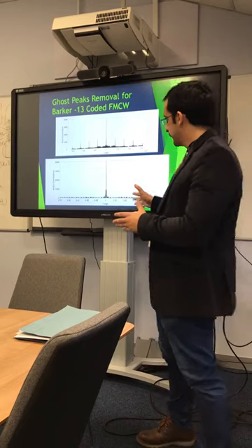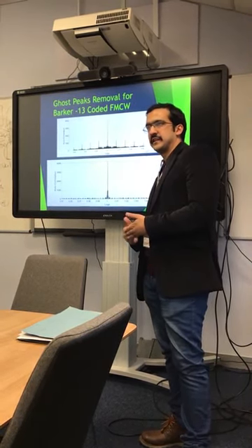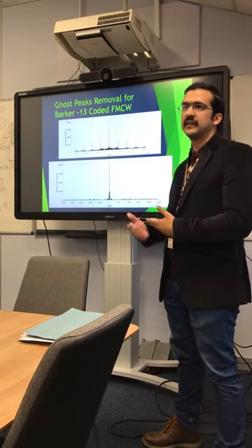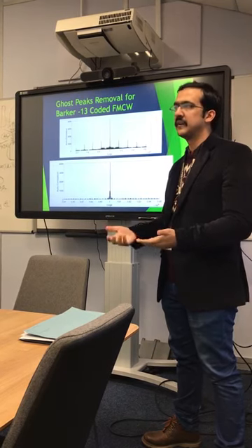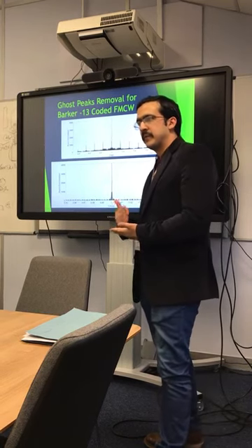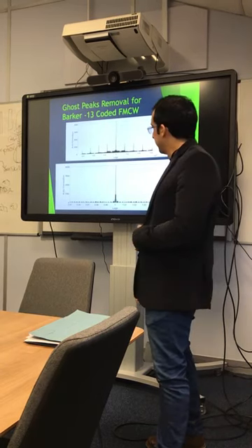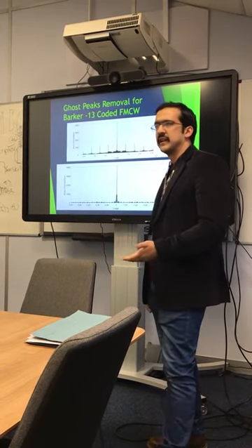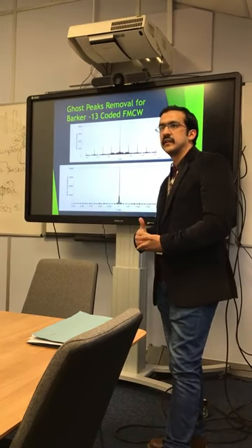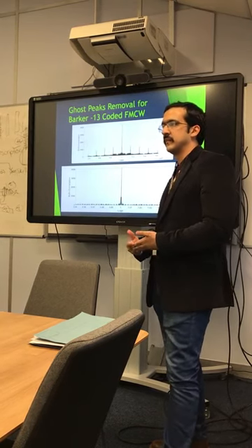The reason to show you a little bit of background of this paper is that using the inherent nature of the FMCW radars and by manipulating the chirp pattern, there is a lot that we can do. A lot of things can be extracted just by manipulating and making use of the chirp pattern of FMCW radar. As you know, there are a lot of modulation patterns like sawtooth and triangular and all those things. Nevertheless, there is a lot of room still for making use of the right FMCW chirp design for some particular application.